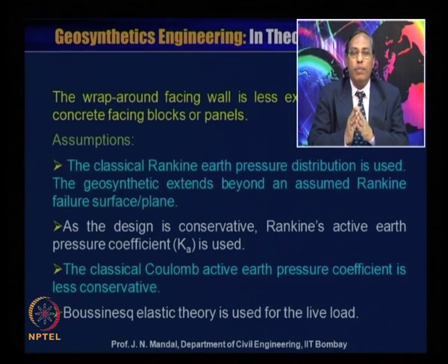Now this design is based on certain assumptions, that is, the classical Rankine earth pressure distribution is used. The geosynthetics extend beyond an assumed Rankine failure surface or plane. As the design is conservative, Rankine active earth pressure coefficient Ka is used. The classical Coulomb active earth pressure coefficient is less conservative. Boussinesq's elastic theory is used for the live load.